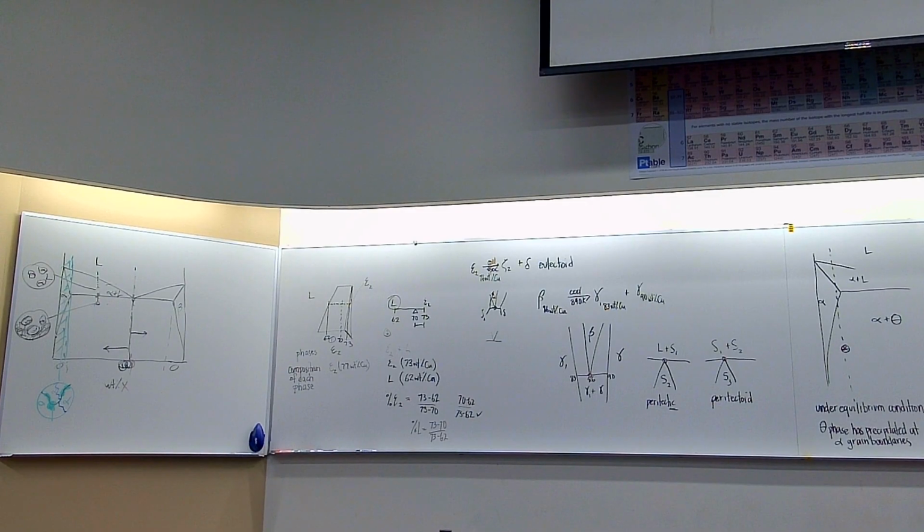Right, there's no eutectic structure, and I create an opportunity for long areas or larger areas of the brittle material, whichever it is. Okay. So we can instead do precipitation strengthening, which is sometimes referred to as age hardening.